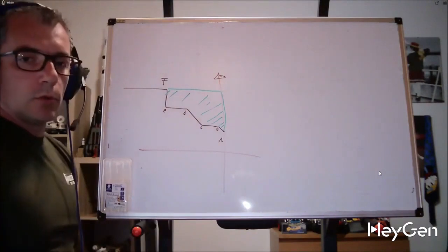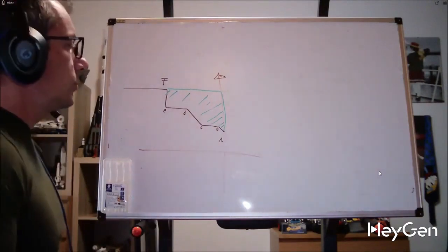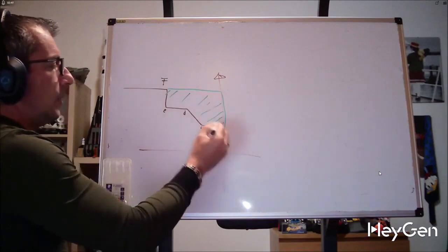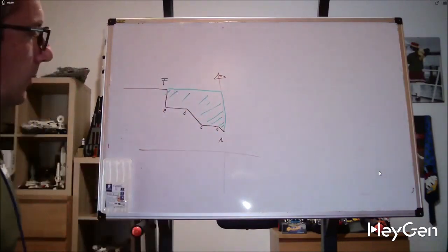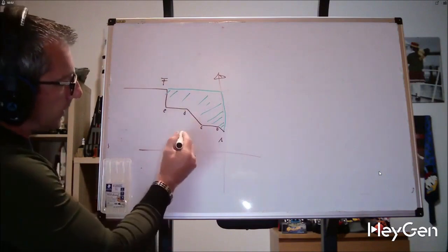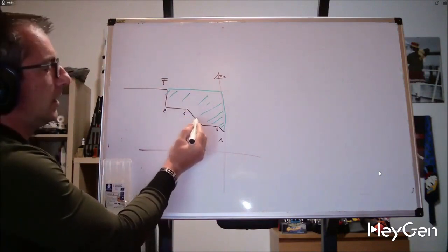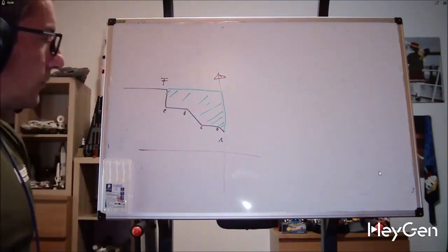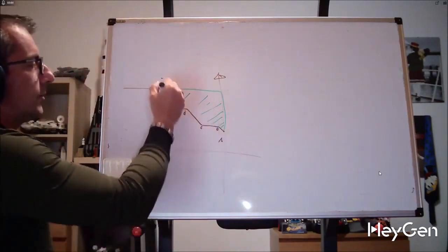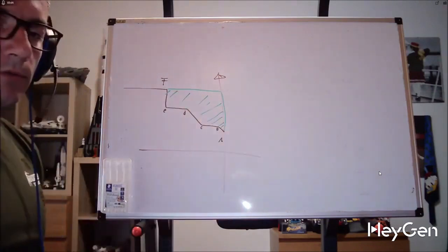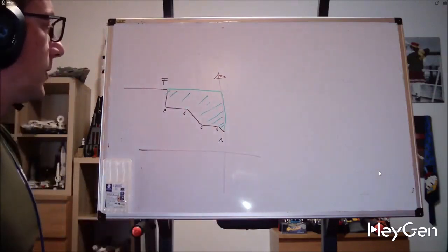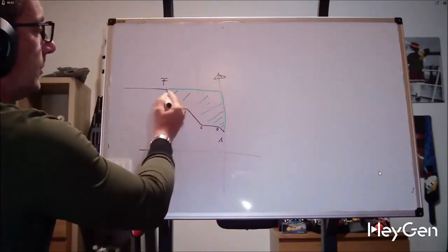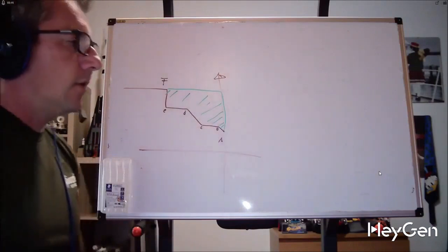Now we know very well, we've seen it in previous tutorials, that point by point we can make a certain number of passes and then describe the profile. It's true that in some places, especially where there are angled profiles, knowing exactly where to stop forces us to do a couple of calculations or to pay a bit more attention. So what does the roughing macro do? It reads the profile and does all these calculations for us. So in 2 blocks we resolve all the steps needed to empty the piece.